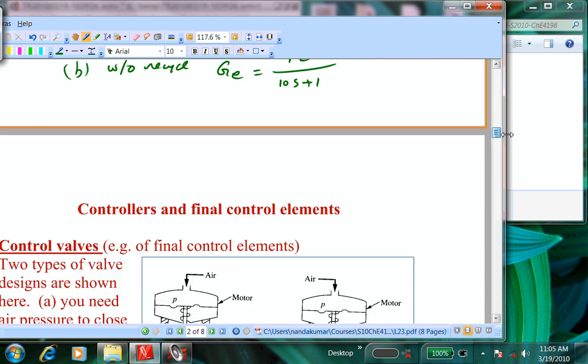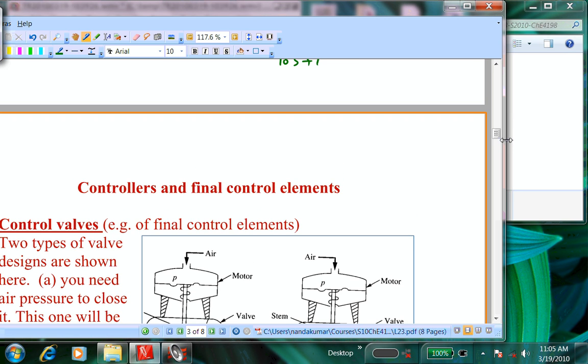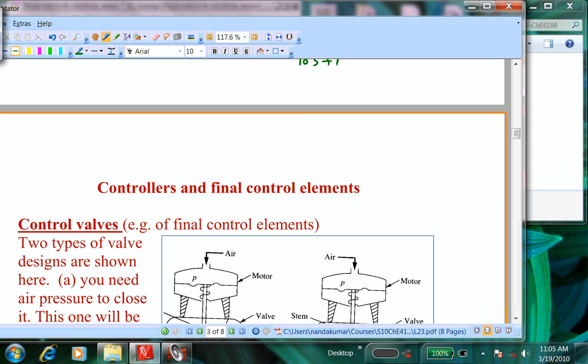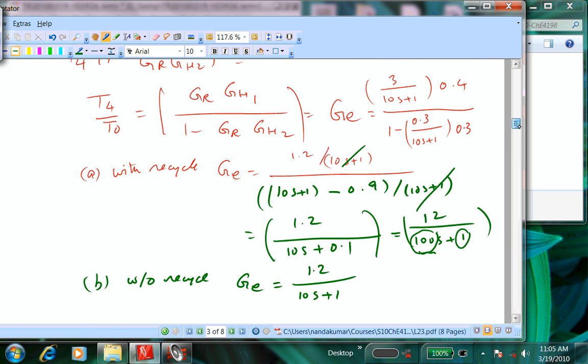So any questions? Do you feel comfortable with that kind of a manipulation in an exam? Well, when you are writing a transfer function, typically you write it as a gain divided by a time constant times s plus 1. Okay. So this is called the gain for the particular transfer function. Once you scale it from 1, then the numerator is the gain.